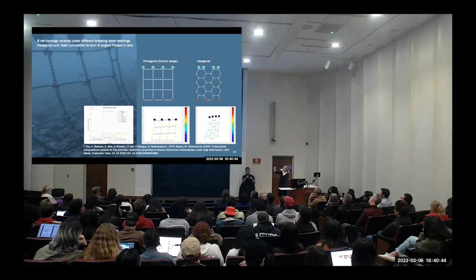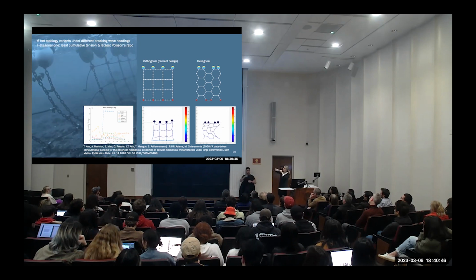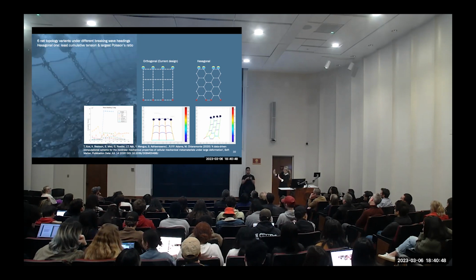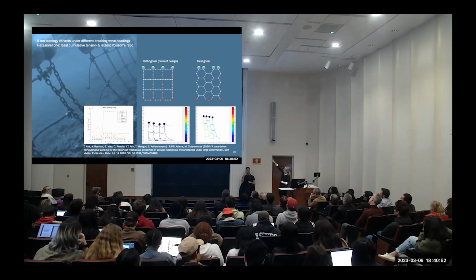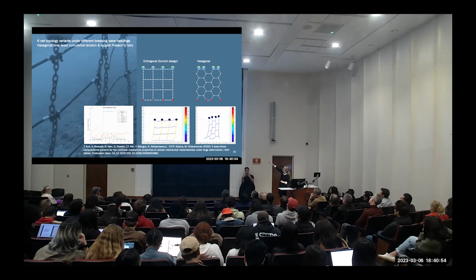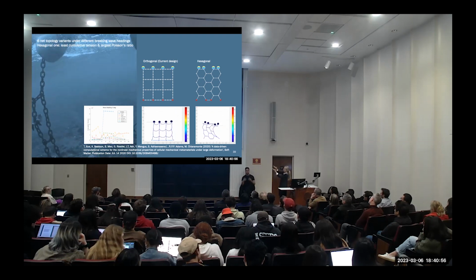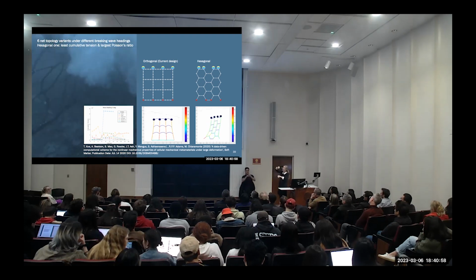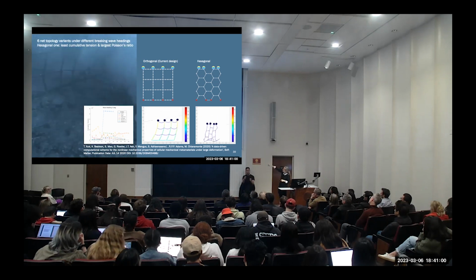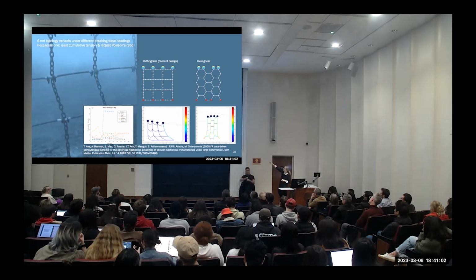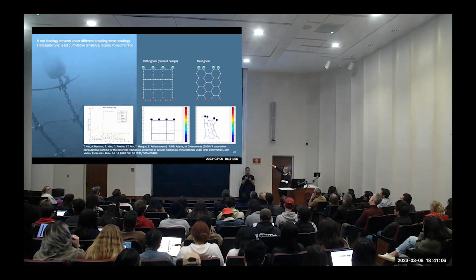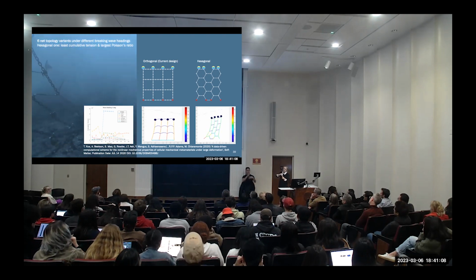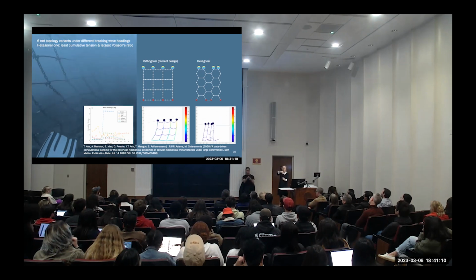And if the net cannot really extend a lot, the tensions in all these cables, in all the vertical cables, become very high. Whereas if you have, for example, a hexagonal net, or if you put the orthogonal net at 45 degrees, then that net can extend a lot. The tensions in the vertical bars are much smaller. And these forces, especially in the orthogonal one, you know, the net didn't break from just one time being in tension,